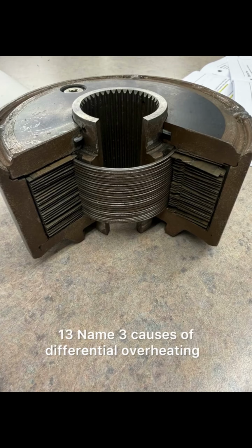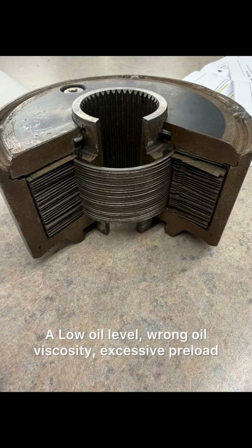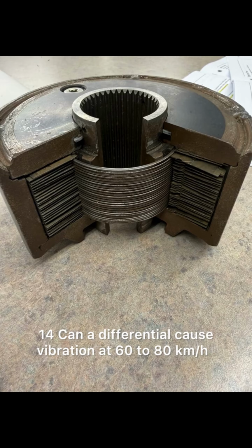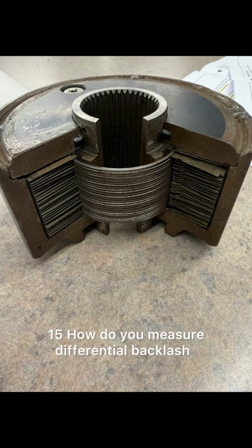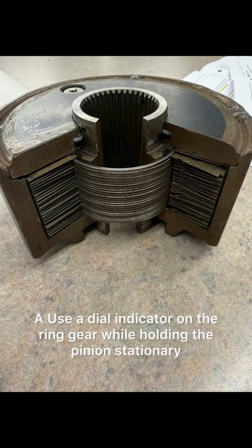13. Name 3 causes of differential overheating. A. Low oil level, wrong oil viscosity, excessive preload. 14. Can a differential cause vibration at 60 to 80 km per hour? A. Usually not. Check drive shaft and U-joints first. 15. How do you measure differential backlash? A. Use a dial indicator on the ring gear while holding the pinion stationary.